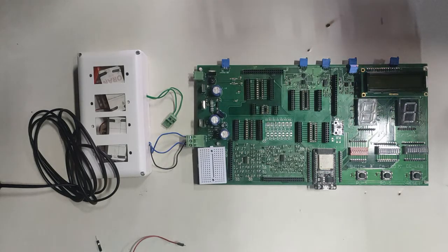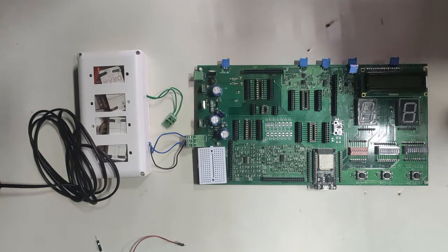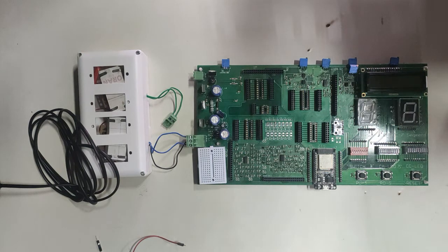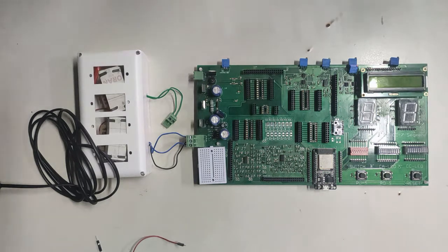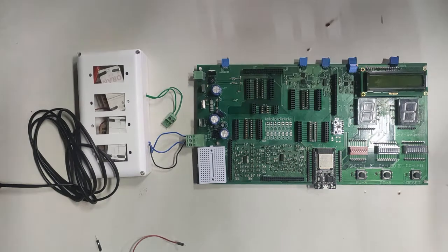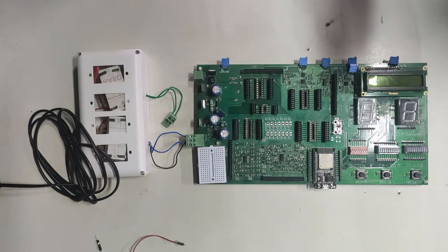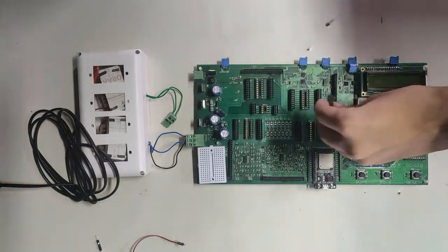In this video, we'll be covering the second experiment of digital electronics, that is to study the universal gates. There are two universal gates, these are NAND and NOR. And the reason we call them universal gates is because we can use them in a variety of combinations to create other gates such as AND, NOT or OR. So in the first case, using the NAND gate, that is IC7400, we'll be creating an OR gate.